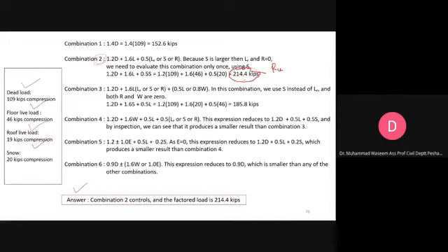Now we know that this Ru in LRFD should be less than or equal to phi Rn. We have this value, which is coming from here. We have been given a phi value, which is 0.9, so if you use this phi value, you will calculate the nominal strength.